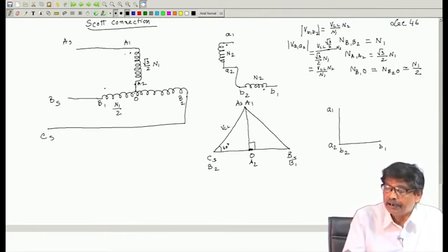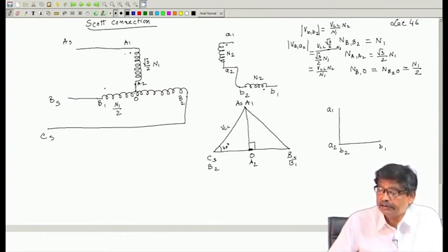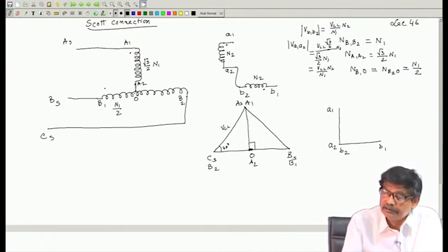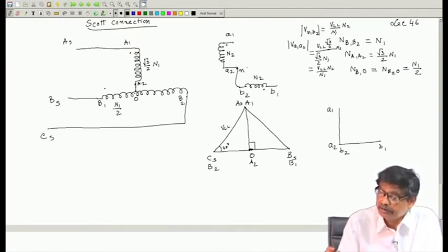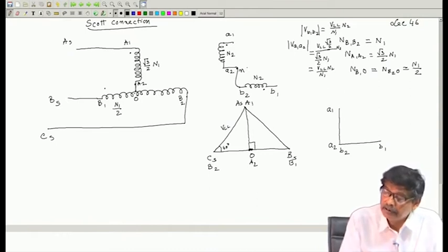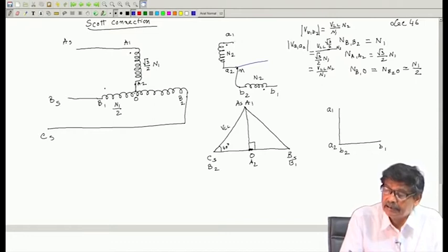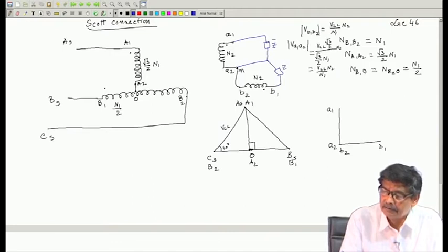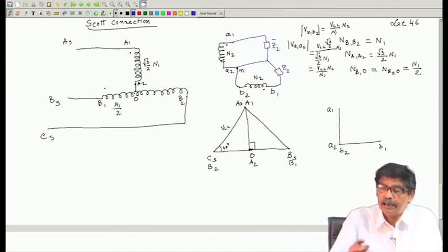Our goal is to get a balanced two phase voltage at the secondary points. So, this is the star point and that is what we did, and then we will connect a load here, say a balanced two phase load. Balanced load, suppose Z bar, and write Z2 to indicate secondary load. So, this is a balanced two phase load and these are the voltages.